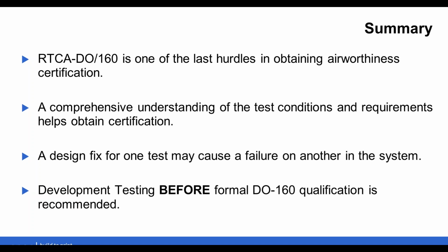Just because you fix a failure does not mean that the fix will not impact another test in another part of the system. It's important to do a careful analysis on any changes when you fix a product, because that may have a ripple effect, or even a negative ripple effect, on other tests within the project. And lastly, we strongly recommend that development testing is done before a formal DO-160 qual so that you have the best chance of passing the test the first time.